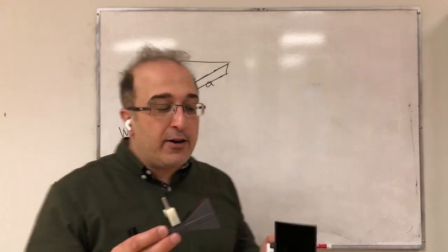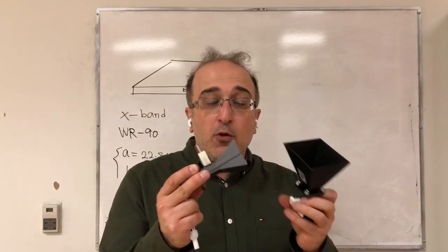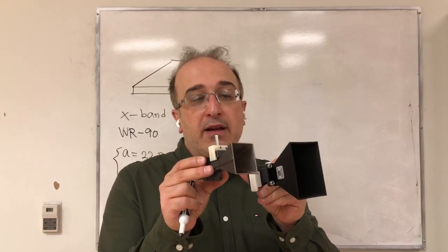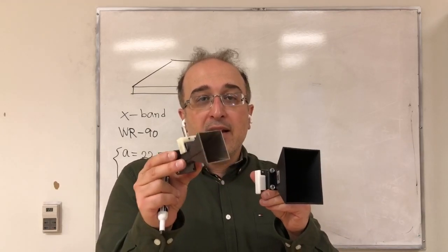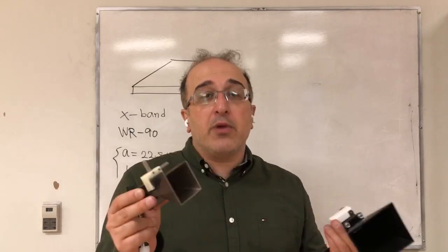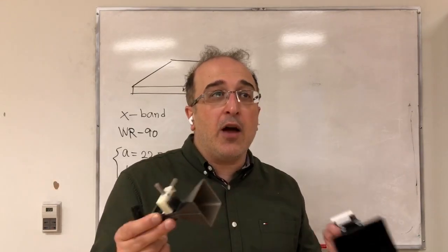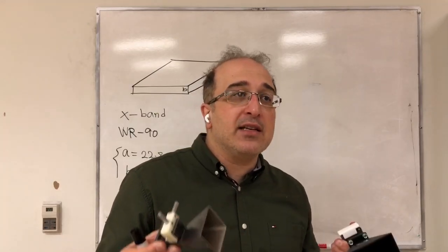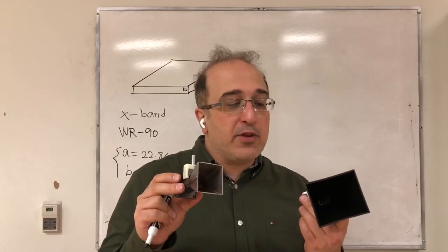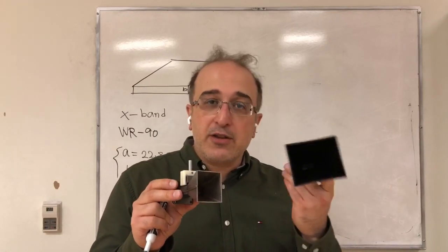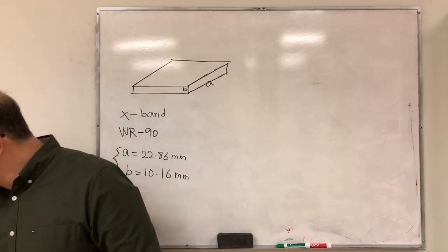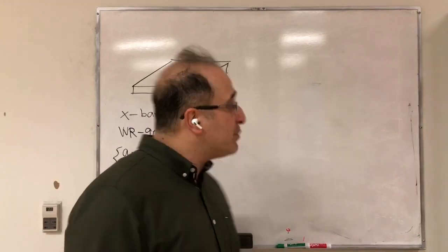With this, you're going to get more directivity. For example, we have this antenna working in the same frequency, but this antenna has a smaller aperture, as you see. So you expect less directivity with this one compared to the bigger horn antenna if they are operating at the same frequency. When you have a smaller horn, the chances are the horn is operating at higher frequency. But in this case they are at the same frequency, so this has a bigger aperture, and this has more directivity. And in fact, you're going to be testing these two antennas in one of the labs.